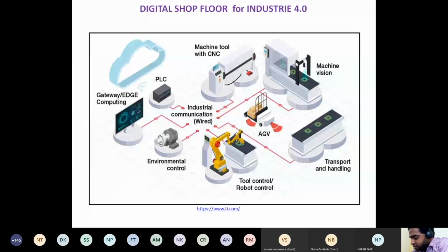Thermal imaging helps teams to visualize how mechanisms are heating or if parts are not running at normal temperatures. The data provided through predictive maintenance technologies can be valuable. Supplier partners can focus time and energy on maintaining equipment based on predicted maintenance events before a problem causes a breakdown.